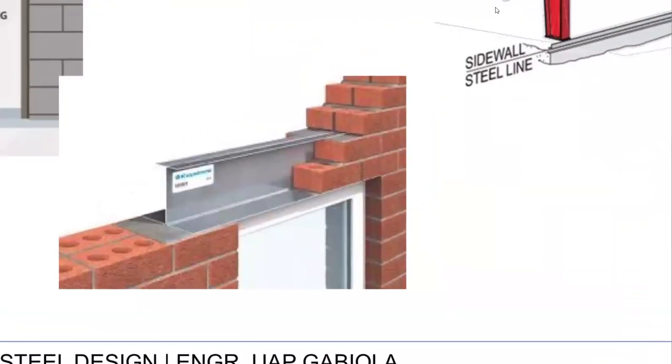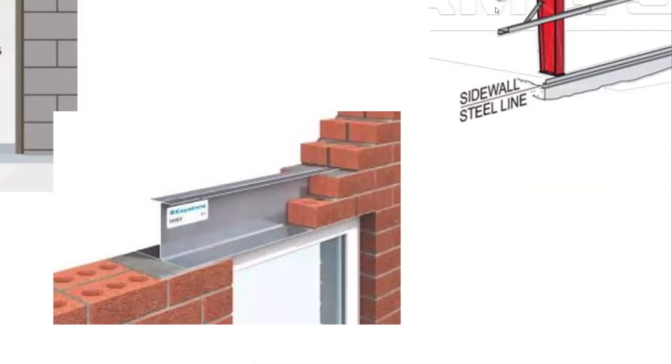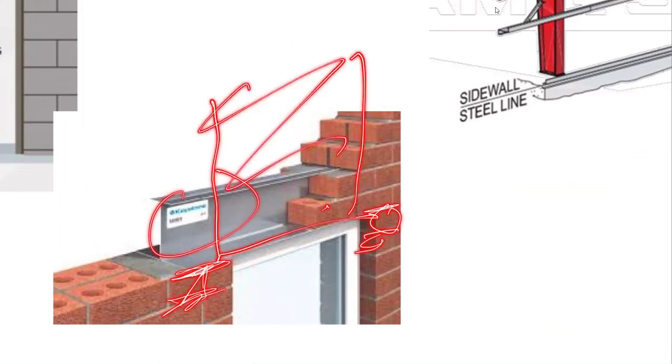It is embedded in the masonry, in this example bricks as our material. You can see above the door that this steel material is offset by some length so that it bears on the masonry, acting like a support. This steel beam carries whatever weight is on this portion.